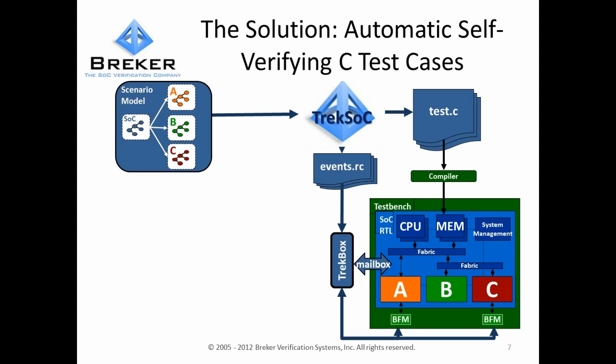At Breker, we said, we're still going to do constrained random verification, but maybe you can introduce a more powerful constraint solver, and we proposed that we're going to introduce a graph-based constraint solver. The idea behind a graph-based constraint solver is we'll have a graph with various decision points, not so different than what Stefan just talked about. Yet we'll be able to put rules on the paths that may be traversed on that graph. If you visit node A, you must visit node B, or if you visit node C, you may not visit node D, and so on. So I want to talk a little bit about how we're going to apply such graphs to verify SoCs.